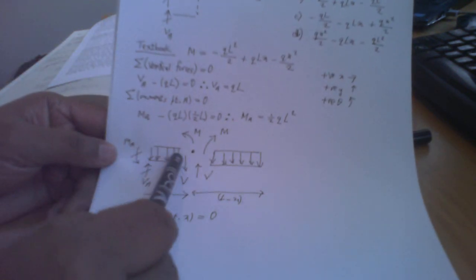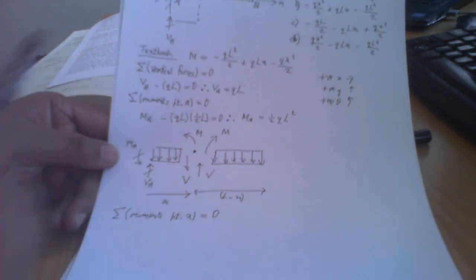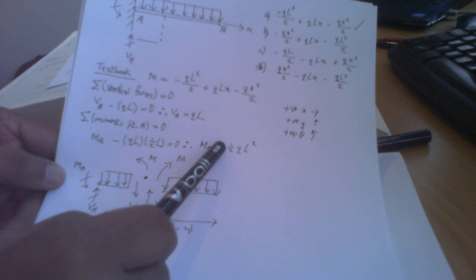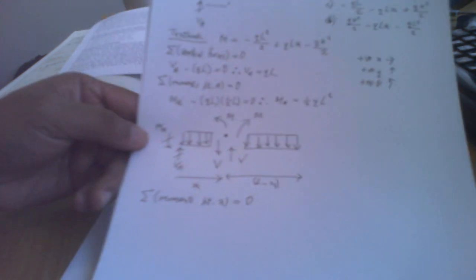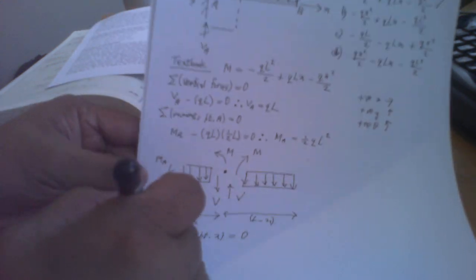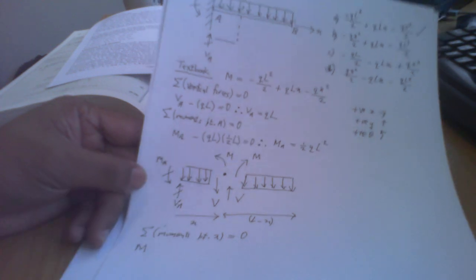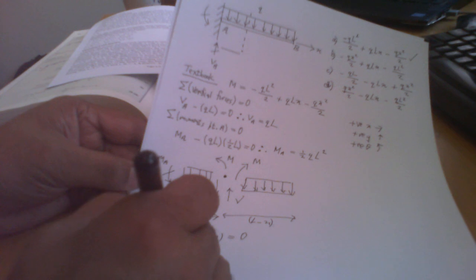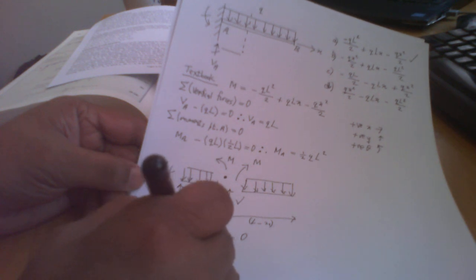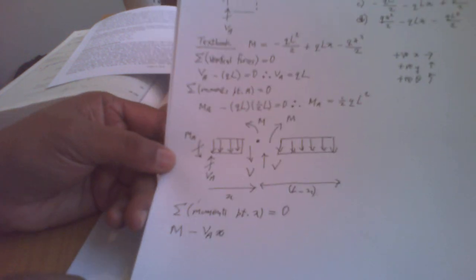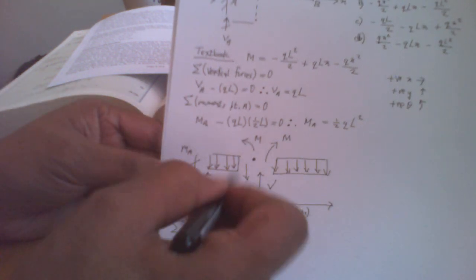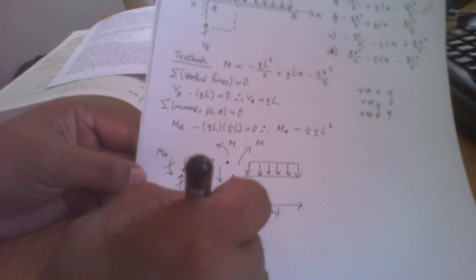It will travel across the beam in an anti-clockwise direction, accounting for the sign convention which we assumed was positive. Apply the equilibrium of moments. M is positive. Shear force doesn't contribute anything. The reaction force contributes a clockwise moment, which would then be negative. The reaction moment would be anti-clockwise, which would then be positive because it's in the same direction.